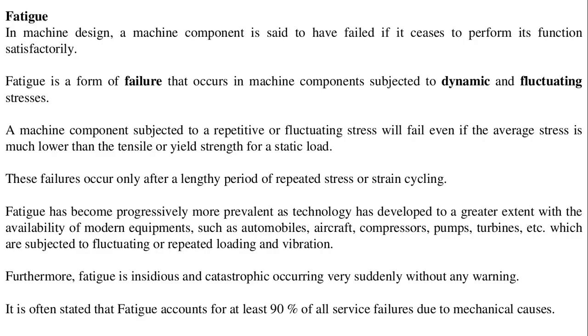Invariably, fatigue failure involves some type of stress concentration in the machine component, which acts as the crack initiation site. Design or manufacturing defects concentrate stresses and reduce the endurance limit, fatigue strength, or fatigue life. Fatigue is insidious and catastrophic, occurring very suddenly without any warning.